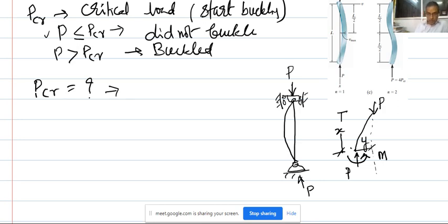So, for the purpose of equilibrium, this is like a bending shape, the bent shape, the equation of equilibrium. So, what I can write is EI d²y/dx² = M, the equation of a member which is bent because of the moment. I am trying to write the moment here, okay, very important. This member has some Young's modulus and some moment of inertia. Now, this can be written in the form of this differential equation, which you have already learnt. So, what is this moment at this particular point?